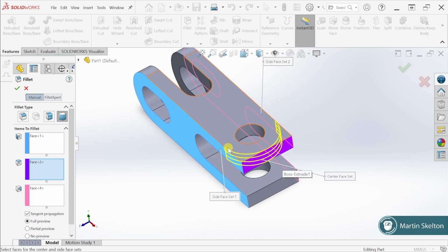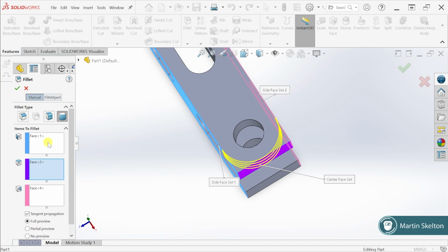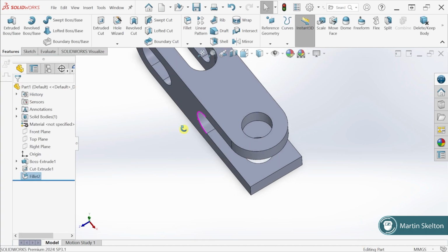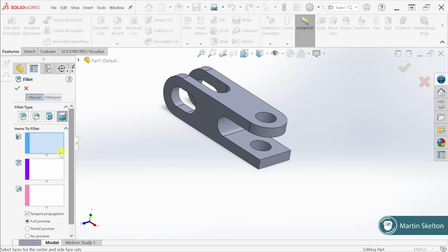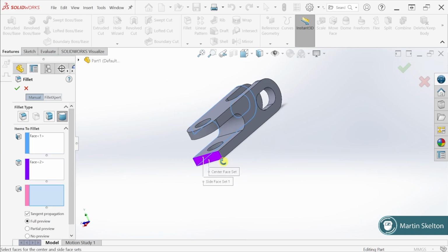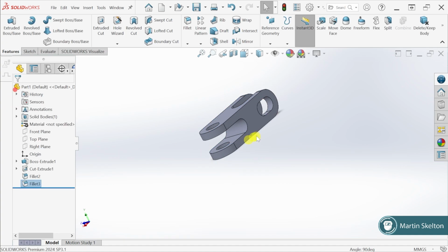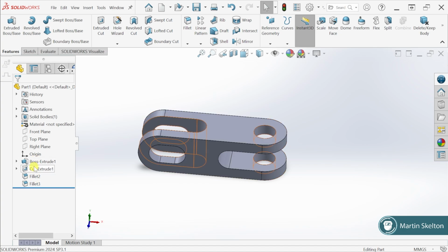As I said, there are other ways of doing this that would reduce features and time associated. If I go back, I have one selected for each and I click. And you can see it has rounded the face in that for me. Well, if I go again with my fillet, very same, 1, 2, 3, and there it's rounded again. Now I have a stack of 2 fillets. There are ways that I could have made that in one move.